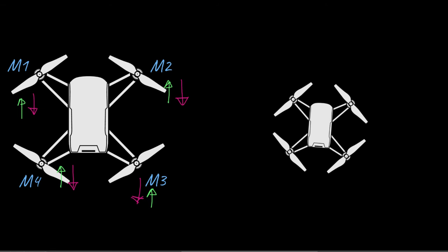In this particular case, you have two quadcopter propellers on the opposite side of the quadcopter, which is motor M1 and motor M3. Those propellers move in one direction, and motor M2 and M4 rotate in a different direction. So M3 and M1 will have the same rotational direction, and M4 and M2 will have the same rotational direction. And this is so that we can counteract the forces.